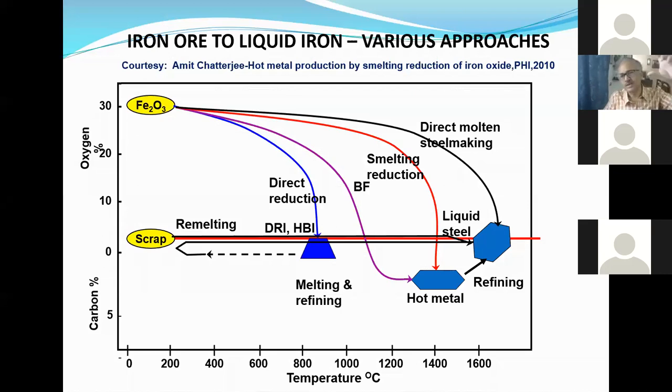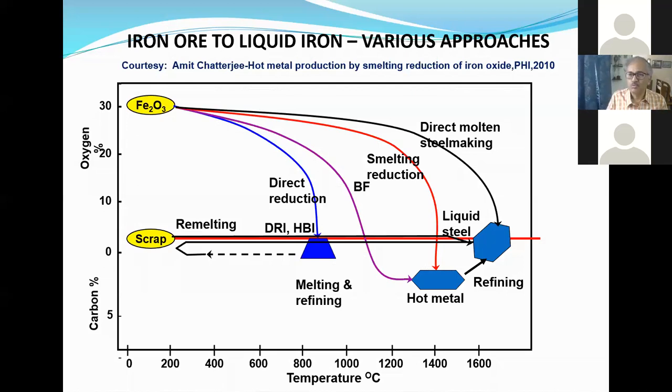So you have a dry zone, you have a wet zone, and that is nicely interfaced by what is called a cohesive zone. But if you want to maintain this very intricate and complex structure in a single reactor, the major problem is that you cannot compromise with the raw material. In the blast furnace, the raw material quality is very stringent, because you are running a very complex process. So the raw material requirement will be very high. That's why the smelting reduction technique comes.